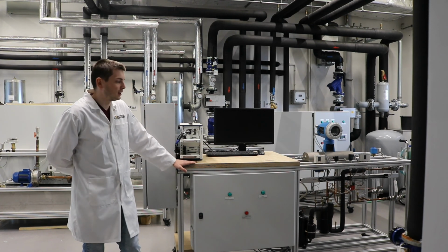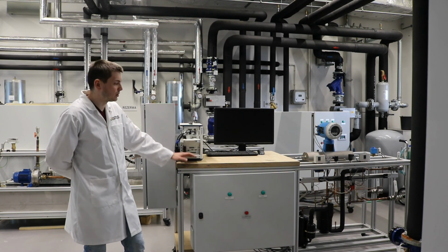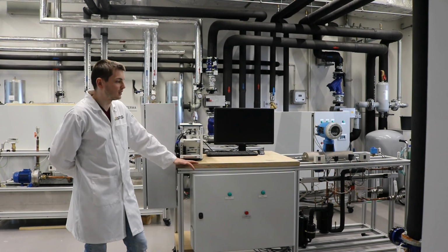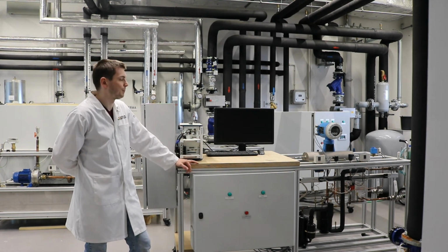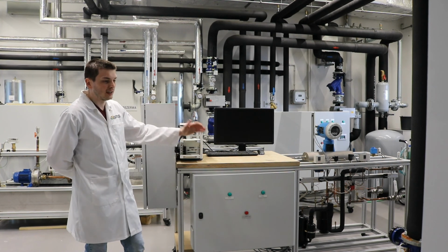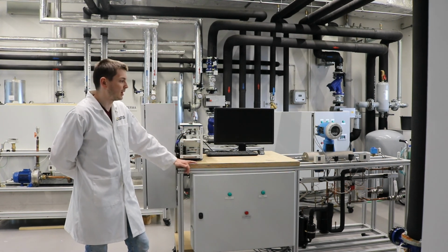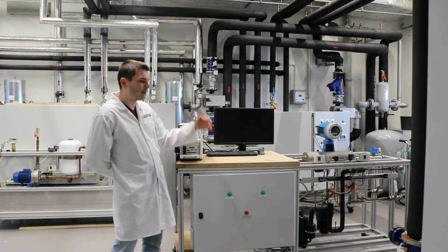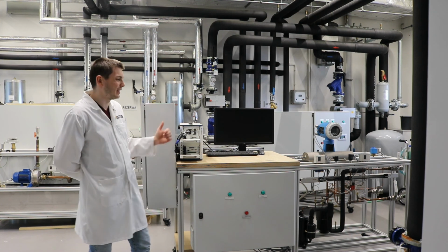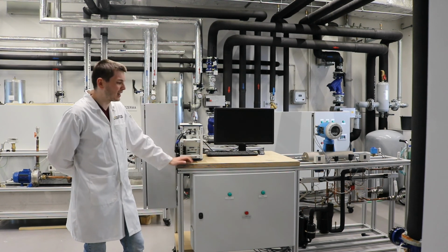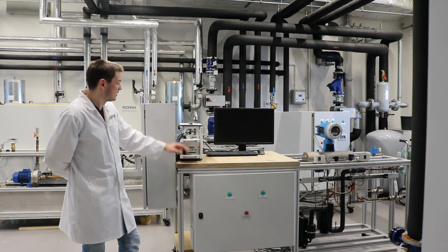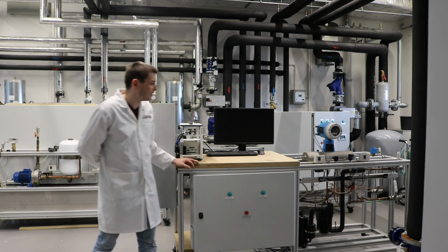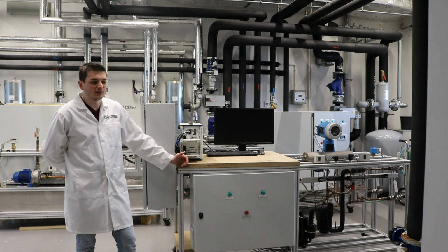What it does is stabilize the upper source and lower source temperature of the water that is supplied to the heat pump. Also, it already takes measurements of these temperatures as well as the mass flow, so that we can calculate the heat flow. Using that, we can save this data using the computer and get this characteristic right.